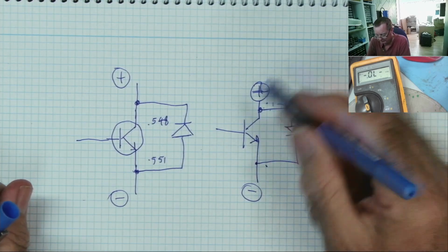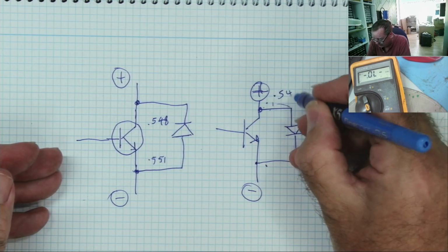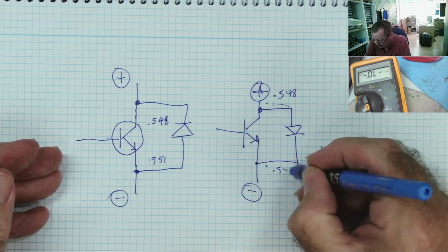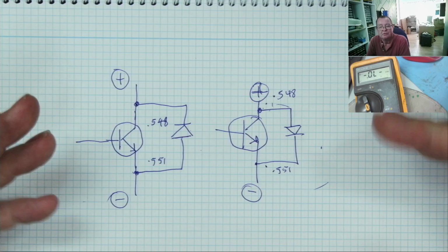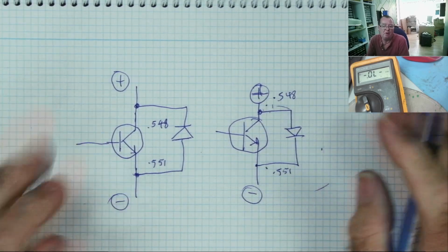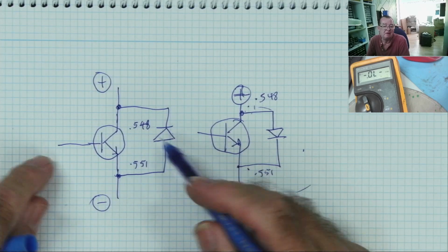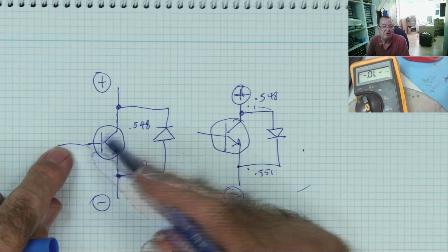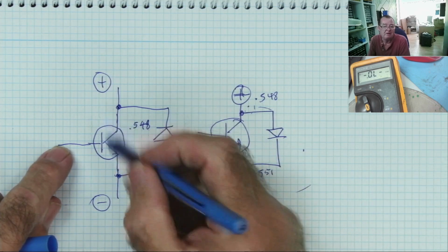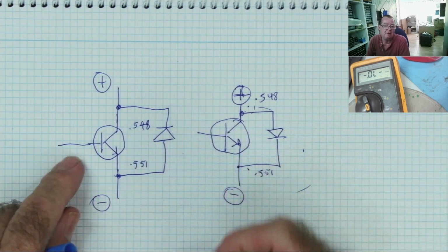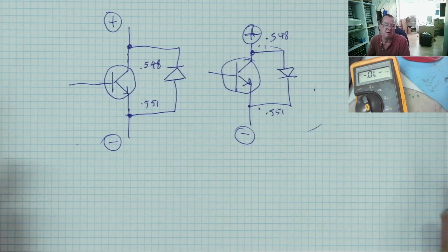Okay, so when you see these strange diodes, put the voltage on so you know which is your base emitter. When you see these strange diode junctions, think about it that way. You don't need to know where the power rails are. If it's a PNP transistor, you'll know because your black lead is on here when it's conducting, and you'll know that the collector on the PNP is going to be negative with respect to the emitter. So the diode junction, if it's something you don't need to worry about, will be the opposite way around.